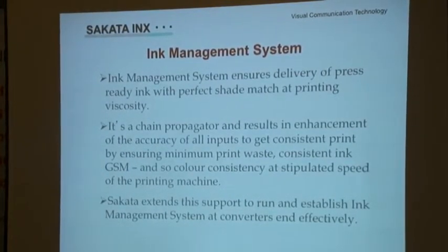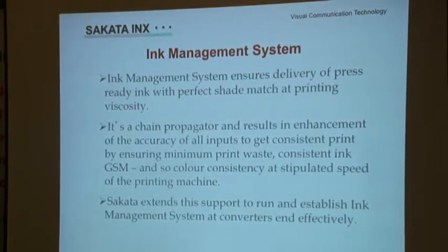If the speed is higher, the cylinder will not be able to transfer all the ink. So you will get the density at lower viscosity. That's why I am saying that when you want the same shade, you need to have this perfect shade at the printing viscosity. And this printing viscosity data you have to have.